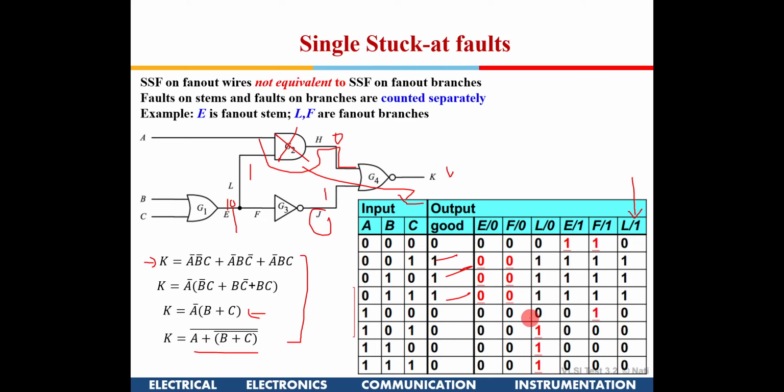So just optimization, yes. See, when we make an algorithm for finding faults at all these locations, and on completion of the algorithm I find that some fault is not being detected, that means in my circuit there is some redundant portion. So testing also helps us find out if there is some portion of the circuit which is redundant. Invariably, if some fault is not being detected, then there is something wrong with the circuit, there is some redundancy somewhere. So that is another aspect of testing which we should remember. Whenever there is some redundancy, there is an issue.